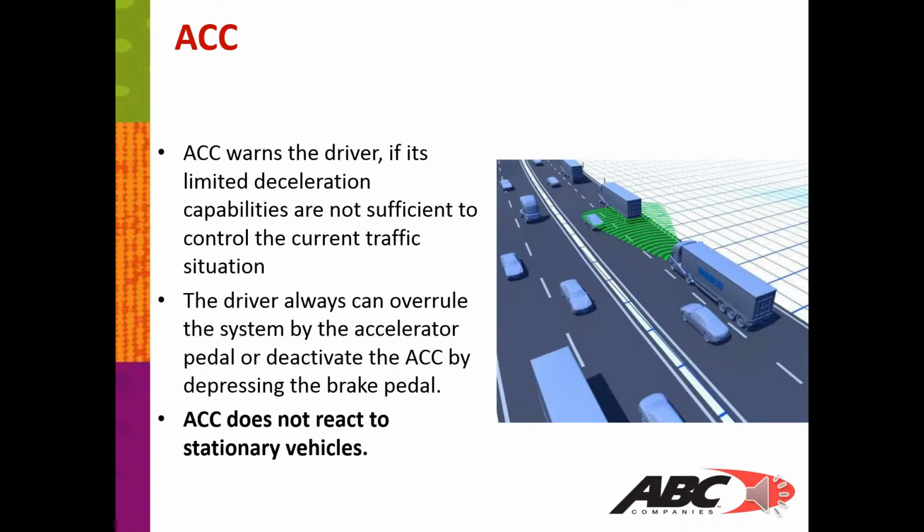ACC warns the driver if its limited deceleration capabilities are not sufficient to control the current traffic situation. The driver can always overrule the system by the accelerator pedal or deactivate the ACC by depressing the brake pedal. ACC does not react to stationary vehicles.